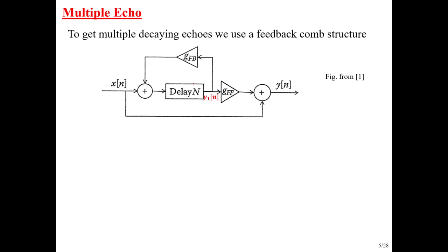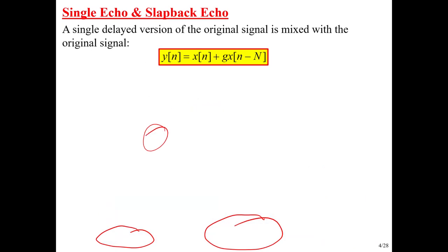So we're going to have a delay of N samples. Again, that N is adjustable by the user. Really we would just lay out a range of memory locations, and then based upon the setting of the delay, we would adjust which value we tap out of. I can go back and show you.